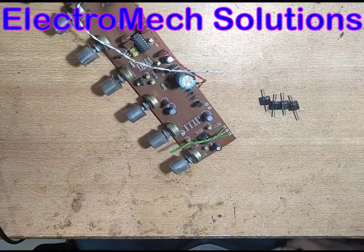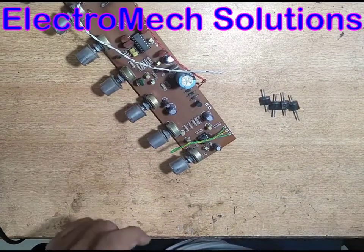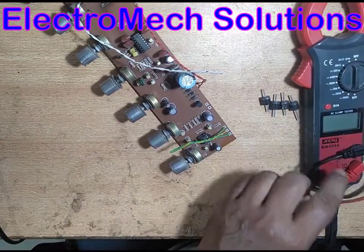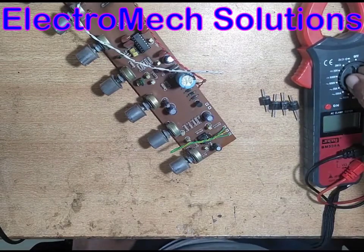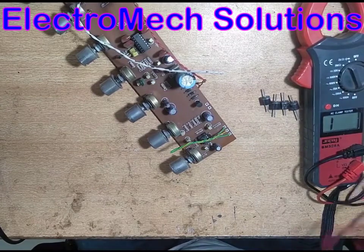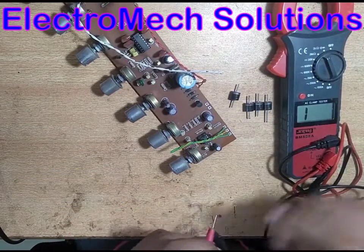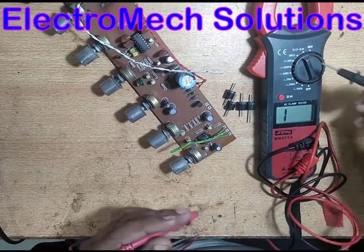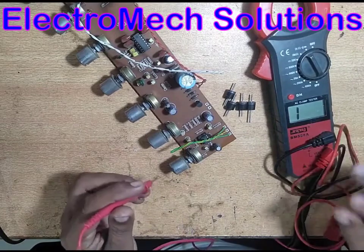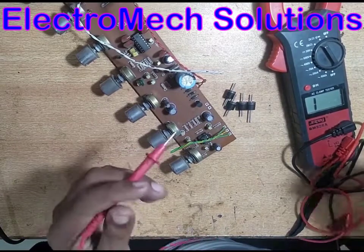Diodes have different sizes according to their current rating. First of all, we need to check the diode. We need a meter, digital multimeter or analog meter. We have a digital multimeter. We need to select the knob of the digital meter at the diode position. This is the symbol of the diode, and you can see the buzzer, the continuity position also. So this position gives us the continuity of anything.